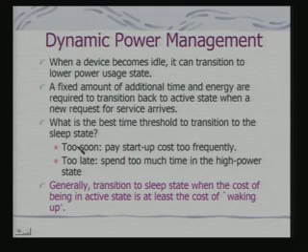So, it says what is the best time threshold to transition to sleep state? Too soon? You pay startup costs too frequently. You may save more power, but you are not saving in terms of time, you are paying in terms of time. Too late, maybe you spend too much time in a high power state when you are not really using it.